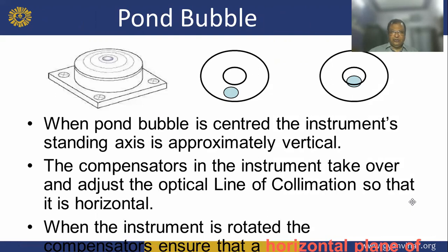Now the pond bubble. When the pond bubble is centered, the instrument standing axis is approximately vertical. See this.